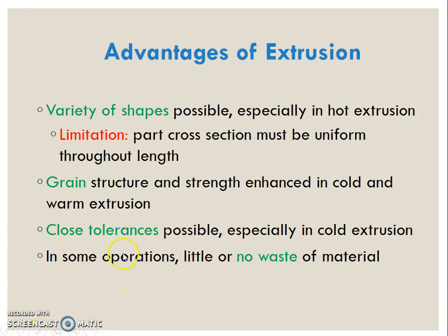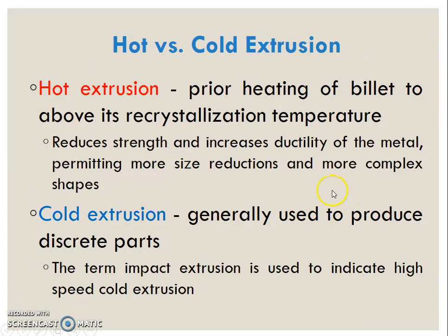In some operations, we can see that little or no waste of material will take place. In terms of temperature, the extrusion also can be performed by using hot extrusion and also cold extrusion. Hot extrusion is usually used for very intricate parts. If the design of the product is very detailed or very intricate, it is suggested for you to use